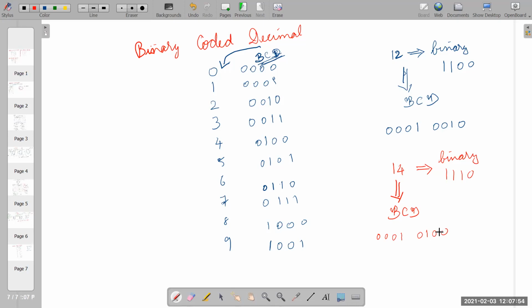Okay. So you are very clear with the binary and BCD. Why do we need BCD also? To drive a 7-segment display, we can see the digital clock. The numbers will be in 7-segment, right? For example, if the time is 10 o'clock, 1 is separate, 0 is separate. In a smartwatch, you see the number 10: 1 is separate, 0 is separate. 12 means 1 is separate, 2 is separate. That is why BCD.